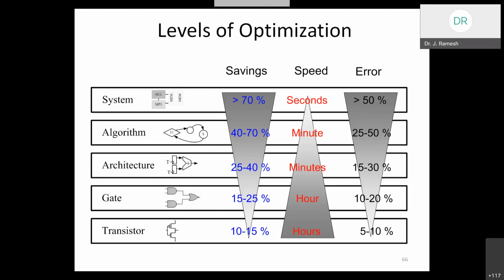There are various techniques which are applied at the architectural or behavioral level of power reduction. And the next one is the logic synthesis or register transfer level. There we can provide proper binary assignments for your FSMs, that is finite state machines, in order to minimize the switching activity. And also, as I told already, retiming can be applied here also at the logic synthesis level.